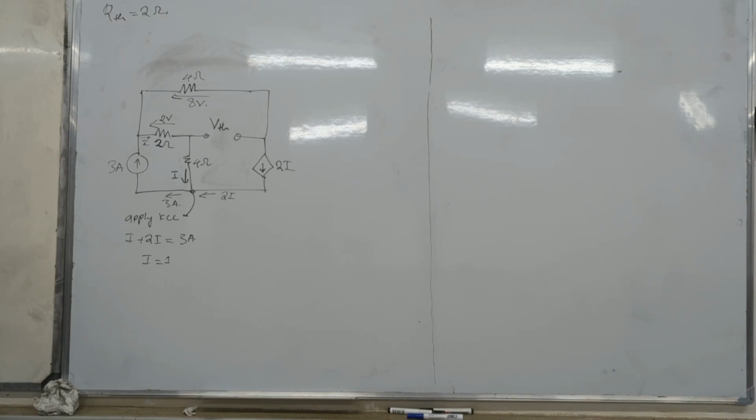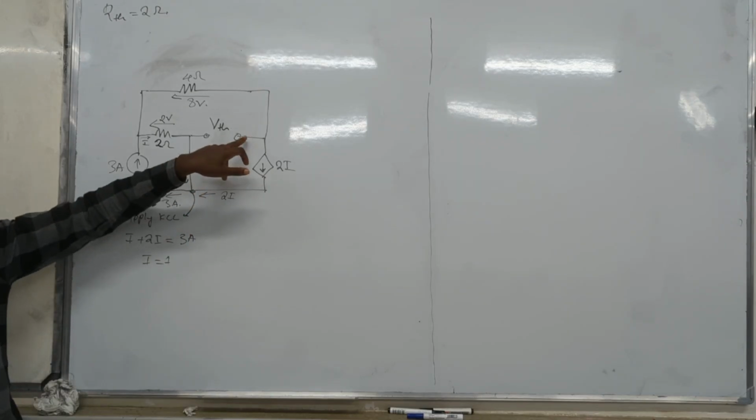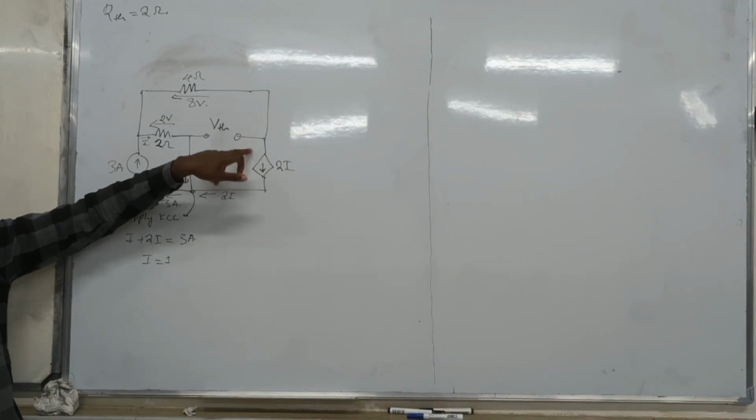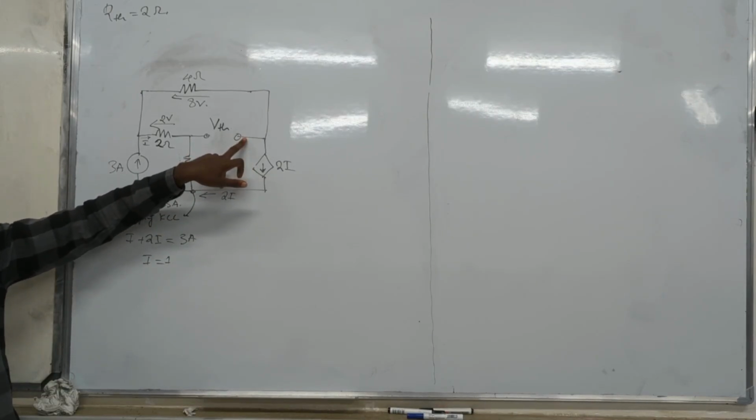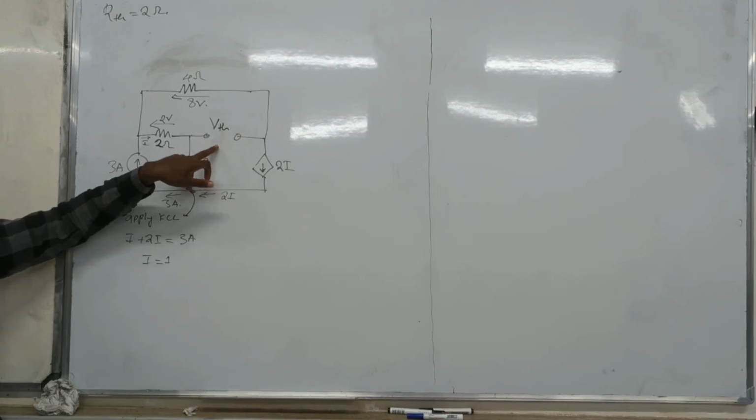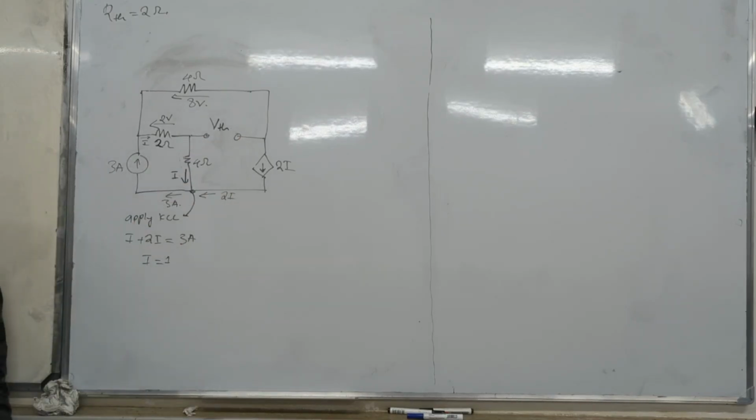Okay. So I think the first strategy when finding voltage across the terminals which are open is you start from this point. If this is 0 volts, I have to walk from this point to the other, and then that's VTH. Yeah, that's applying KVL.